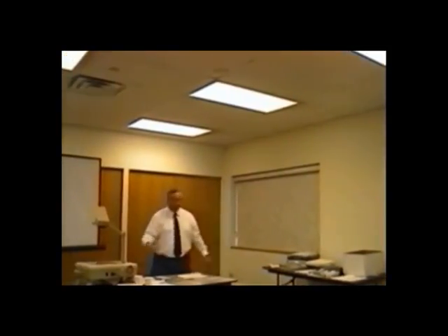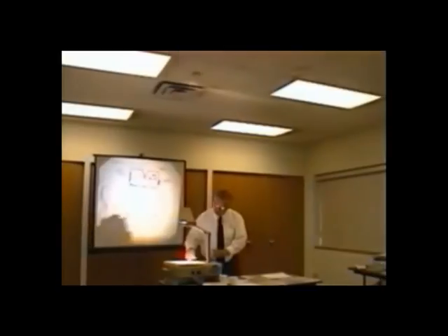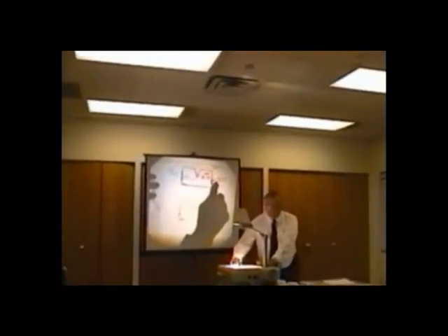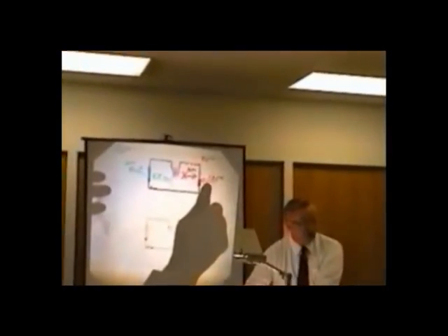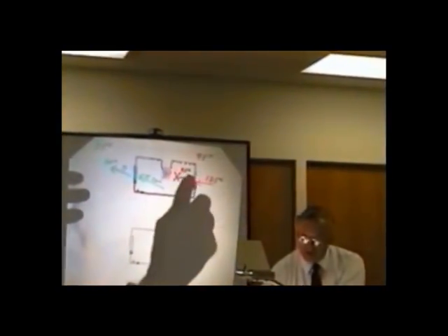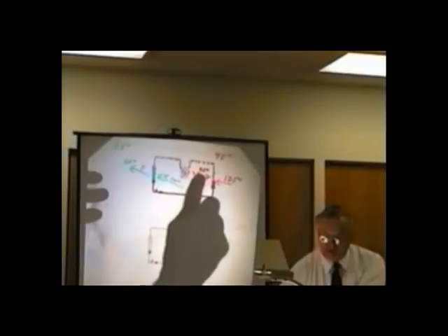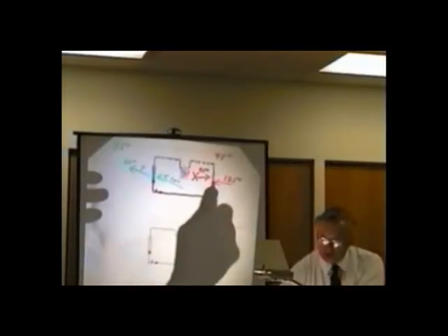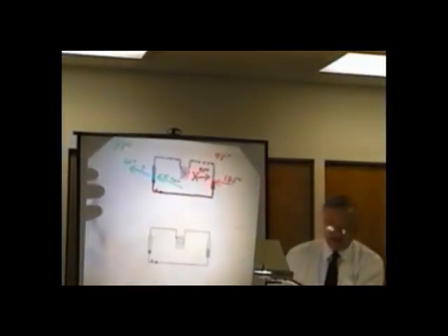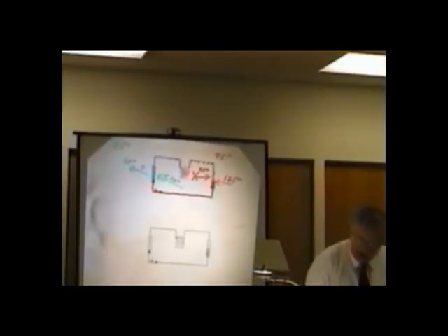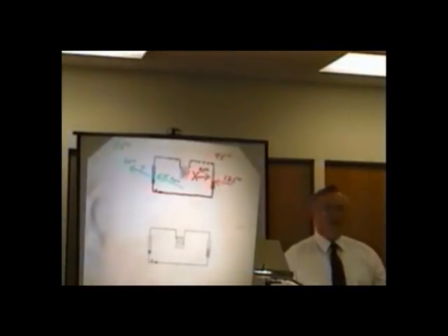But we don't care about that temperature. What we're concerned about is, let's go back to the overhead, the saturation temperature. This is the temperature, again, where the refrigerant is changing state. Remember, we have the gas giving up BTUs to the cool air, and so it condenses into liquid. We said that it's 125 degrees. How do we know it's 125 degrees? Just because I said that?